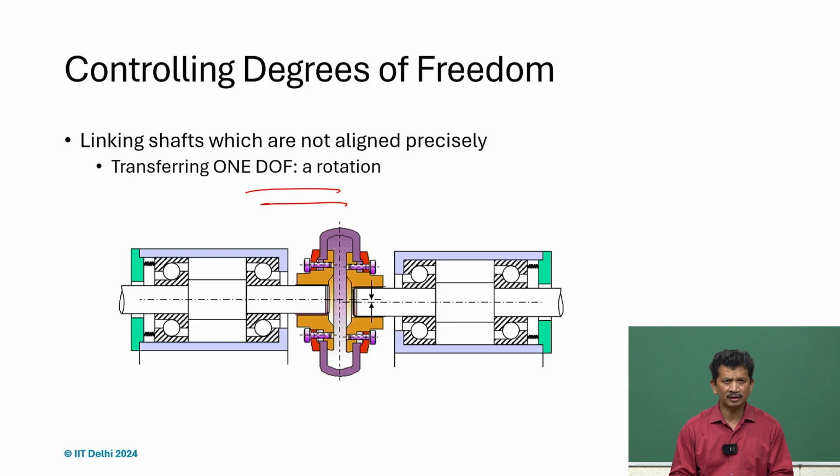So, a very common application where we want to rotate one component with respect to the other, and when we are looking for applications where we have to point devices, we have to rotate precisely, and sometimes these numbers can be very small, maybe of the order of arc seconds. And what we realize is that if we are looking at those numbers, friction and any kind of rolling contact may not be good. So, in that case the coupling has to be proper, and we can use an exact constraint design approach, and then we will see that we can eliminate friction related problems, the virtual backlash, the hysteresis part.